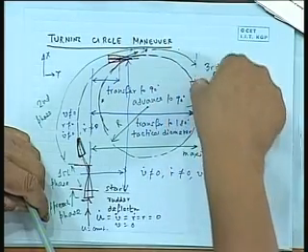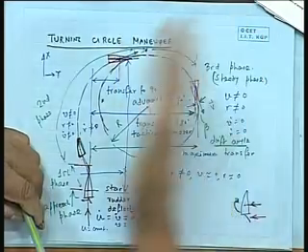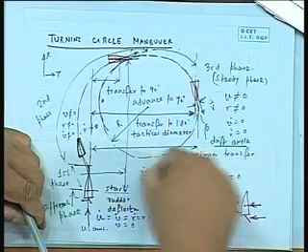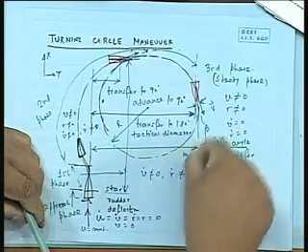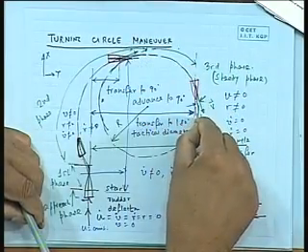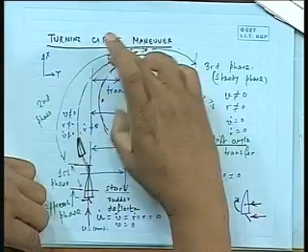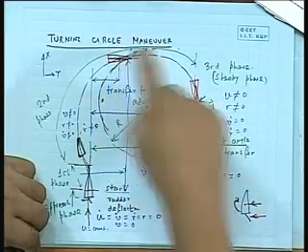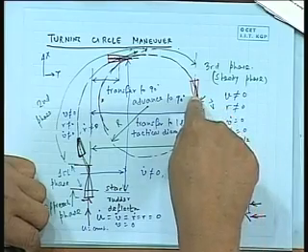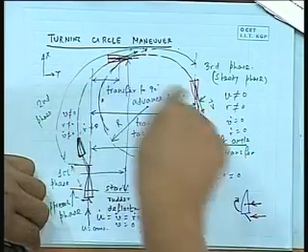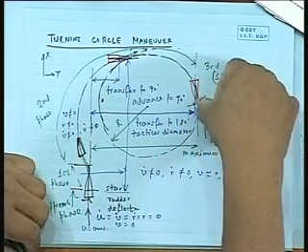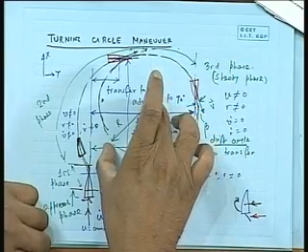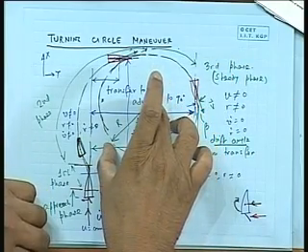Similarly here, when it changes to 180 degree, you see how much it has shifted that side. Essentially you take this radius; ultimately we will see the radius, but these are the measures you actually have. So you have the two point measurement, 90 degree heading and 180 degree heading angle, so x and y distance of that. You measure also the speed here, you measure of course this drift angle, and finally you measure the steady turning radius. That is the most important thing that you measure.